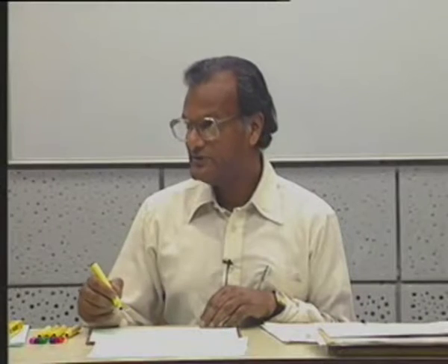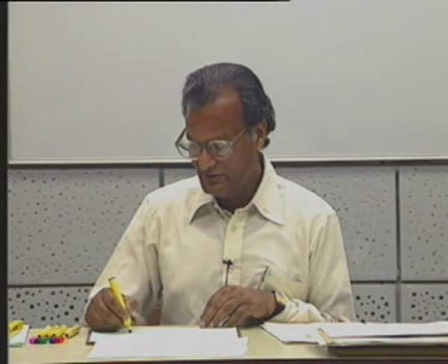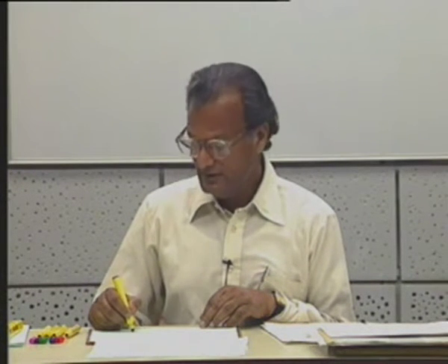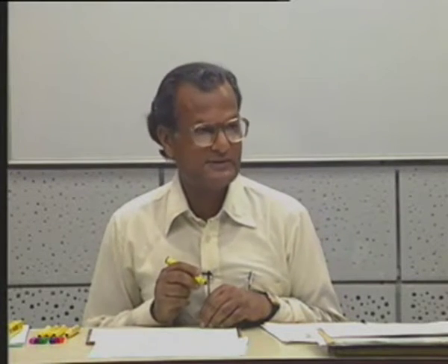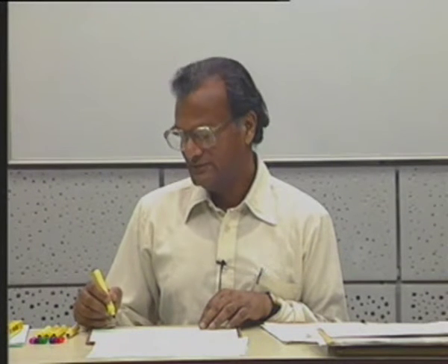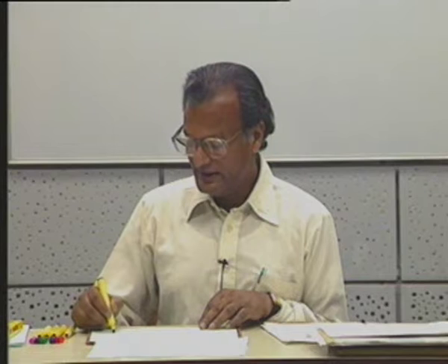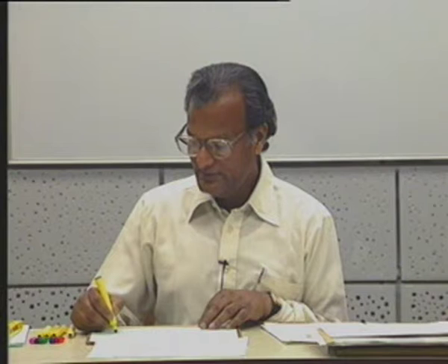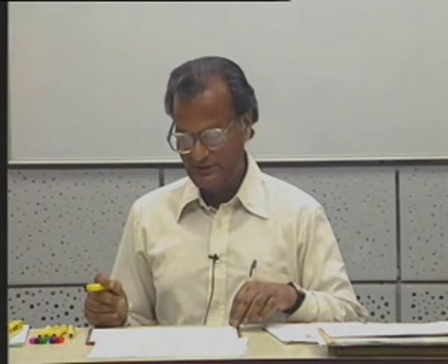This is, as we had already found out, 0.025 divided by capital I subscript capital B. It is the DC value of the base current. Usually this relationship is written in terms of collector current. So, if I put I sub C here, naturally I should multiply this by beta, beta times 0.025 divided by I sub C. This is the value of R pi, and you see R pi depends on the Q point. R pi depends on the collector current at the Q point, all right.